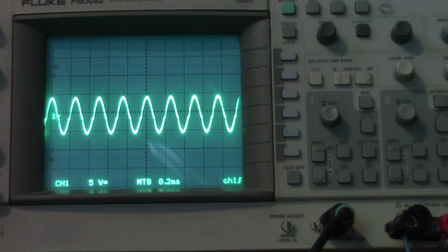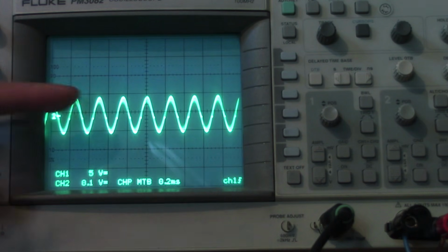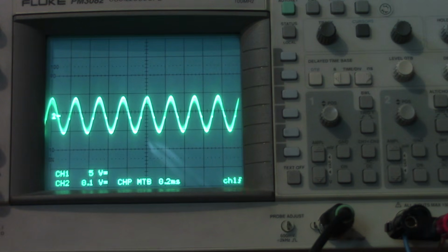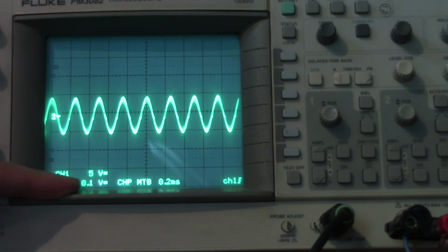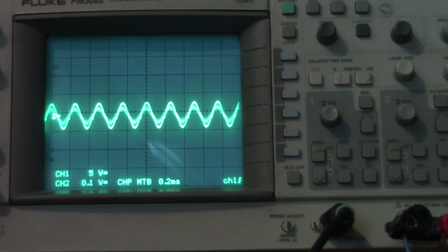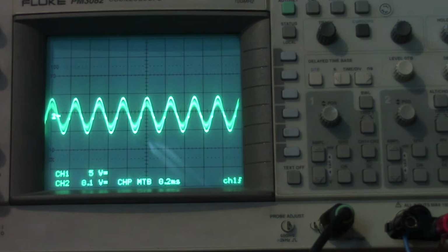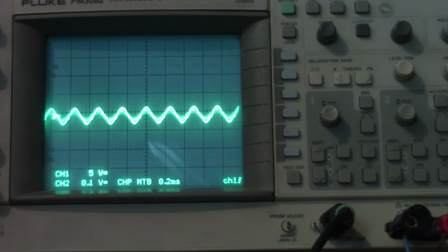Right, so what I'm going to do now is turn both channels on again so we can see them at the same time. Right now they happen to be almost perfectly overlapping, although of course they're at vastly different scales, so it doesn't mean they have the same voltage in an absolute sense. So now watch what happens when I start messing around with the volume on my phone. If I lower the volume, you can see that it lowers both the output and the input signal. So it just scales in a linear way, which you might expect from an amplifier with a fixed gain.